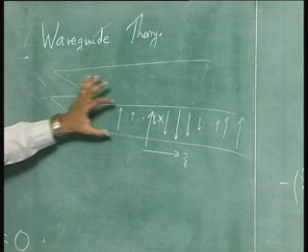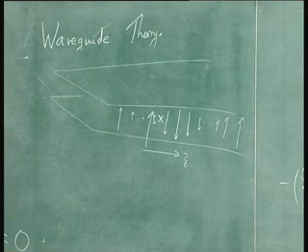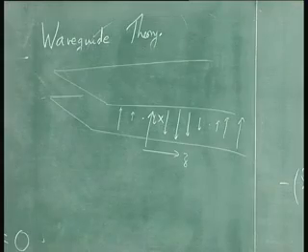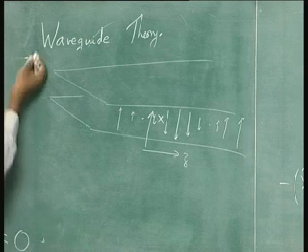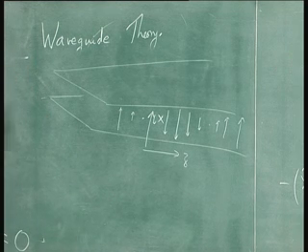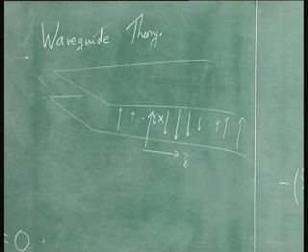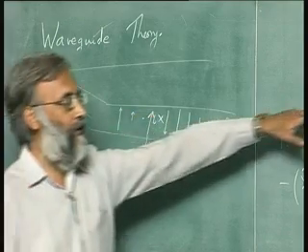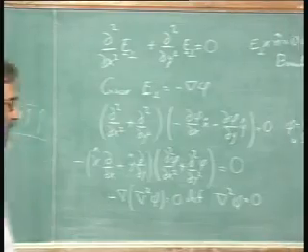Now I want to convert from electric and magnetic fields to voltages and currents, because that is what circuits know, and that is what is that equation. The equation has to do with inductors and capacitors. Well, the idea is we have solved for a potential. We looked for E equals minus grad phi.